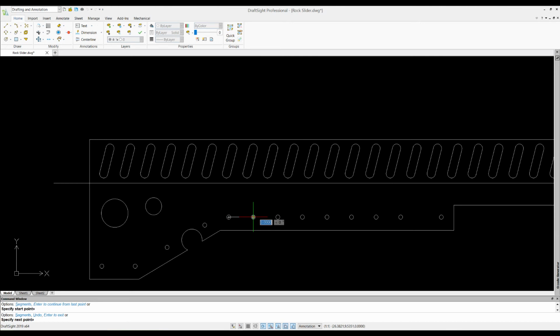So we want them in the middle. So snap the middle, and that was 3 inches, remember? So we'll go 1.5. And then up to there is 3.875, but actually that's irrelevant. We need it to be kind of closer to that. So let's center them, 2.625. So that's 2 5/8. And then now we can just go over. We know 6. Actually, let's just go 12, because we can also snap to center.